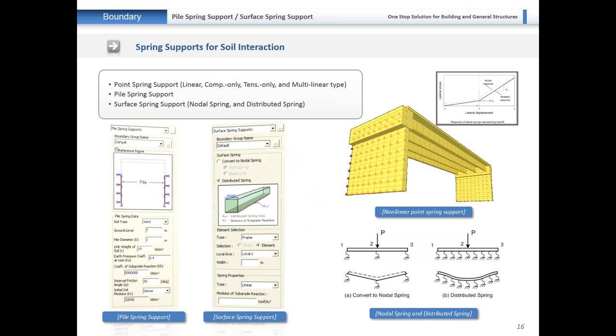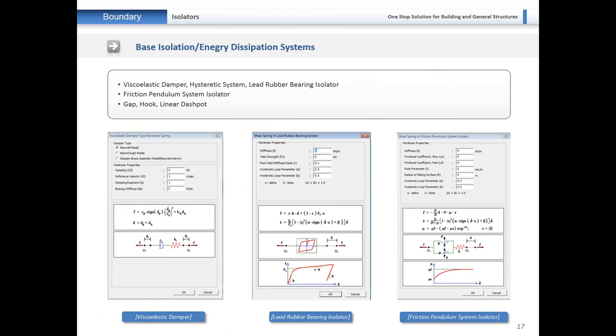Various types of options we have. See, this is one type of shear wall under the ground. If pressure loads are coming onto the shear wall, we can define the supports for that type also. And for the pile, generally if you model the pile, because of the lateral soil, negative friction is generated. That you can also consider at the time of modeling. Generally this is used for soil structure interaction, meaning if your building goes underground, you can study the effect of soil on your structure.